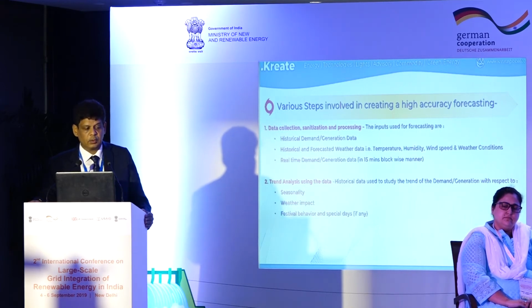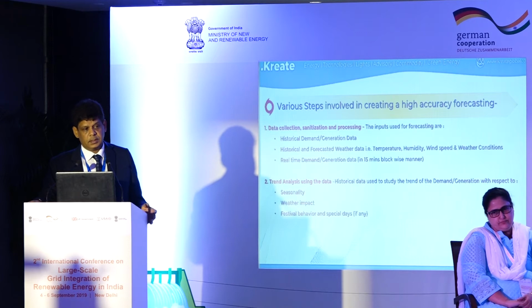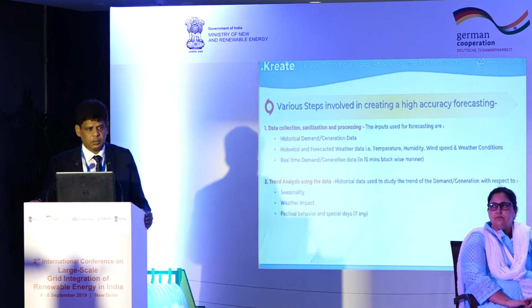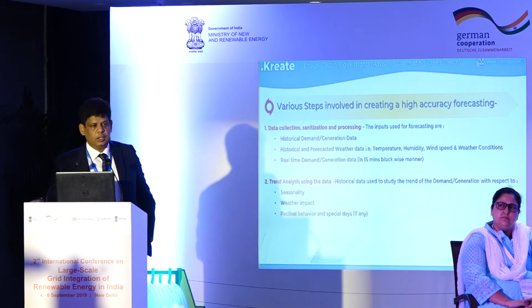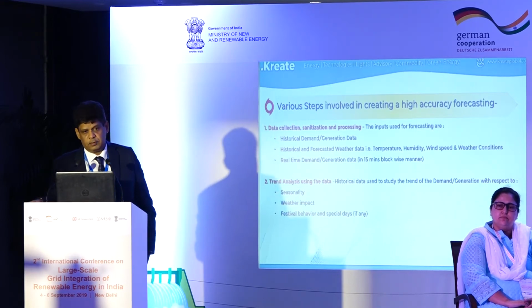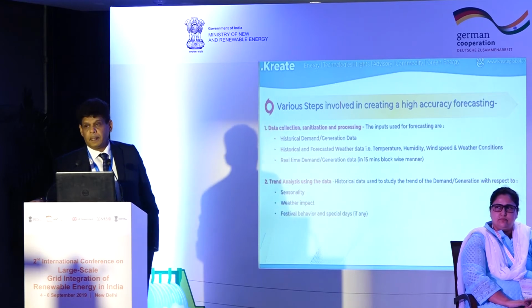It's getting more difficult to handle the size of data. And then based on the data, there is a trend analysis done, which studies the seasonalities and the impact of the weather. For example, a 1 degree increase in temperature during the summer peak can increase the daily load by 500 to 600 megawatt. So these are significant impacts, and you need to understand and analyze them beforehand.